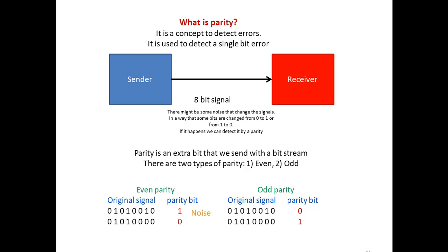Remember I told you that the baud rate is important. The baud rate is the speed at which data bits are sent from the sender to the receiver. This is important because it is a property of your instrument. When you purchase an instrument, the manufacturer will tell you the baud rate. So you have to know the baud rate, and then define it in your LabView program.